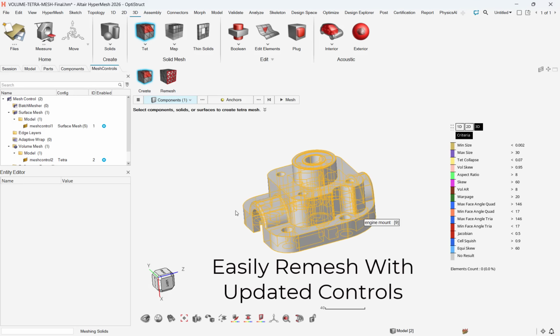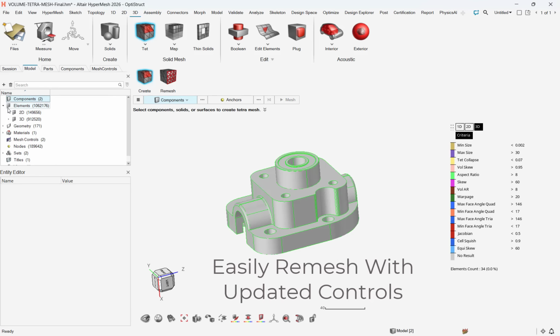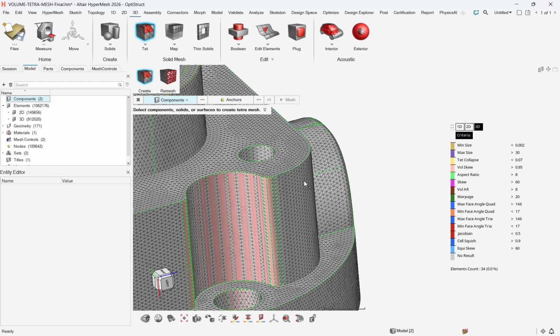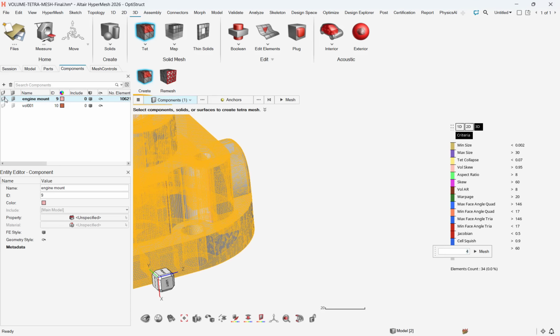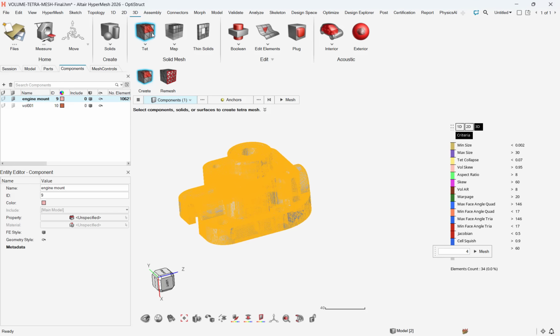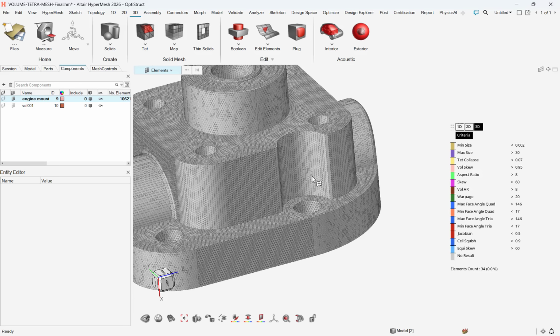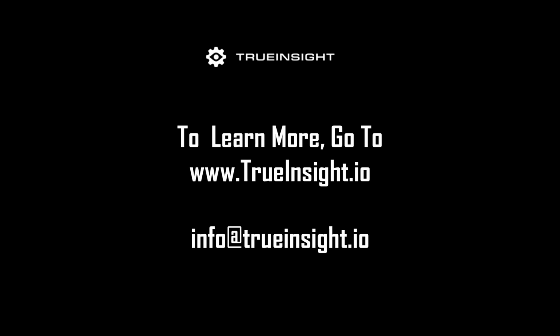After generating the mesh, I can see on the one element face there is a much better density of Tetra mesh. I was able to do this without adding a bunch of extra global Tetra elements, which is advantageous computationally for my future simulation. With Hypermesh's 3D Tetra meshing options and controls, users can easily create advanced meshes in seconds.